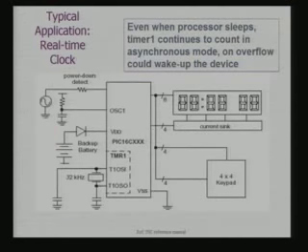Now this is a typical application of a timer. I can build a real time clock using this timer operating in asynchronous mode. Because in an asynchronous mode the timer needs to count, and I can actually put my processor to sleep.